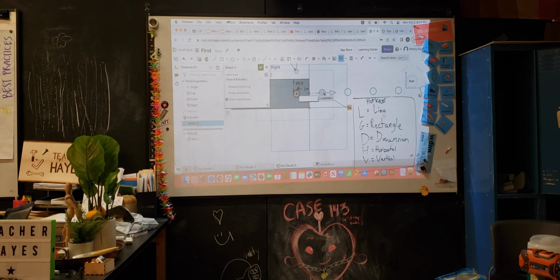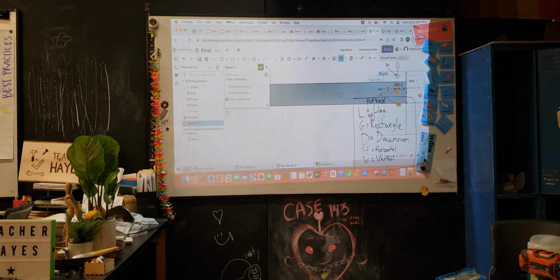So what I do is I click -2 and I'll flip the direction. Alright. So look what I got right here. Instead of manually creating all these holes and dimensioning between each of them, I did it all in one swoop using the linear pattern tool. So then you can click check, and boom, got it there.